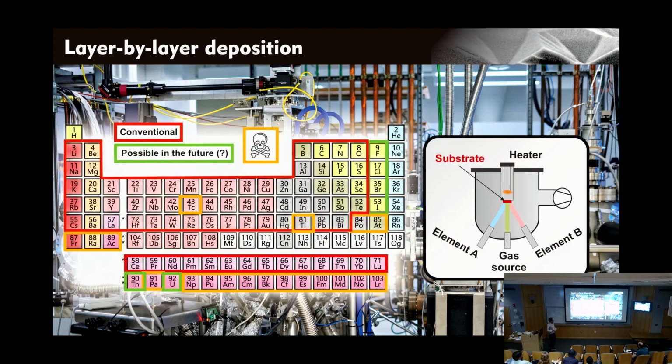And basically, the idea is that in thin film epitaxy, we take this high vacuum chamber and we evaporate stuff onto the surface of a substrate, which we can choose from commercial vendors, based on the lattice constants, the lattice symmetries, the surface energies, these types of things. And we deposit the materials that we want on the front side, and we do this at an elevated temperature, and we synthesize them.